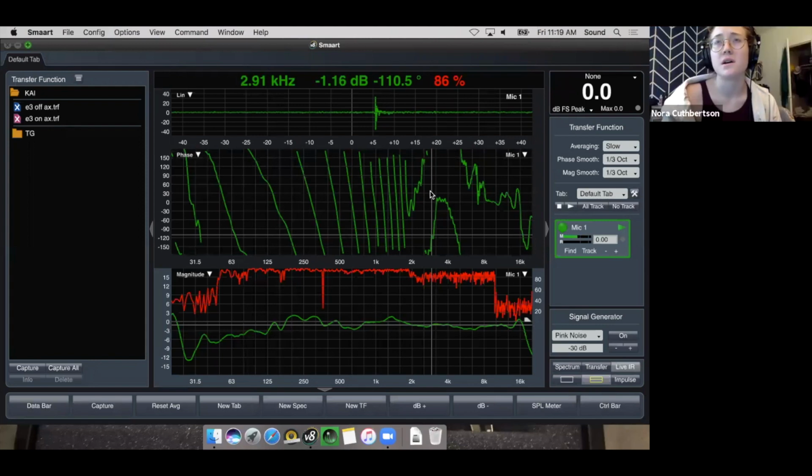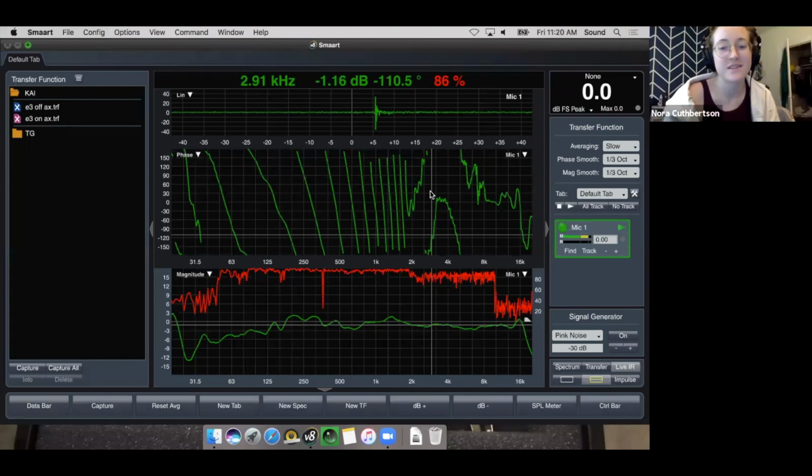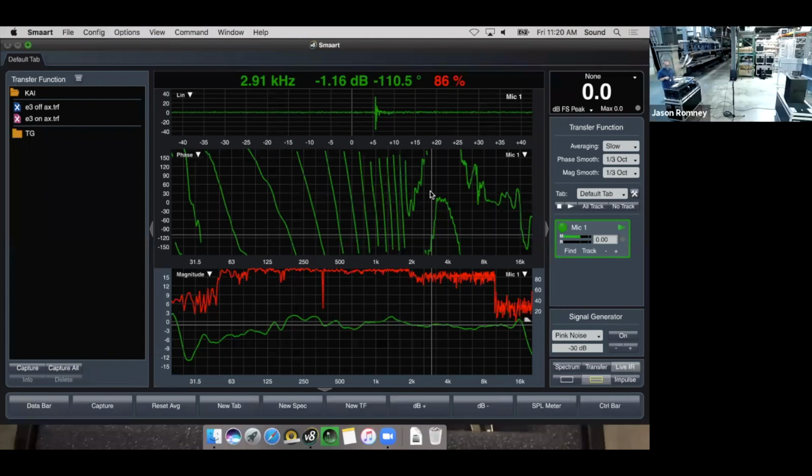Cables, your processors. Yeah. Software too. Air. Yeah. Sure. Air, literal air. Yeah, exactly. So we've got this pink noise coming out of the audio interface. It's going into this amplifier, and the amplifier has a digital processor in it, which means it's probably going to pick up a millisecond of latency, right? It's going to take this amplifier a millisecond to get the sound out. So there's a millisecond we've picked up in latency.